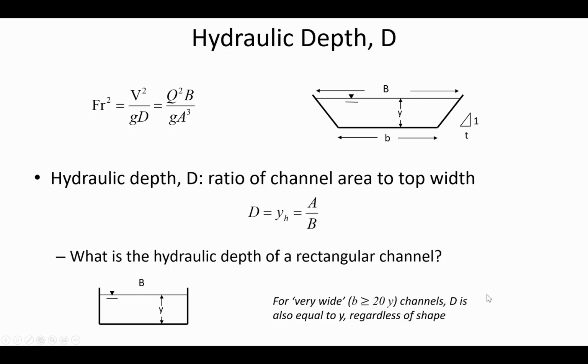Now, I also put in this preliminary note here, and we're going to talk more about this in the future, but if a channel is really wide, meaning that its width is more than 20 times greater than its depth, then the hydraulic depth is also just equal to its depth, Y.